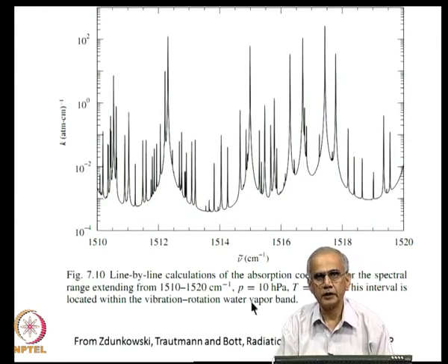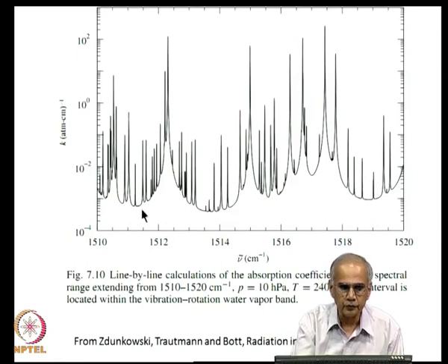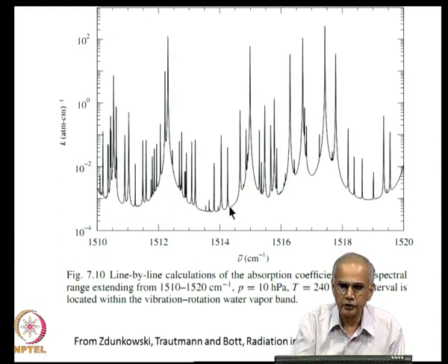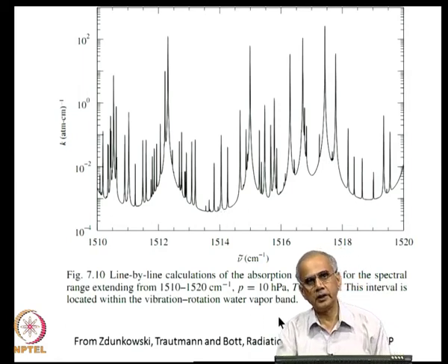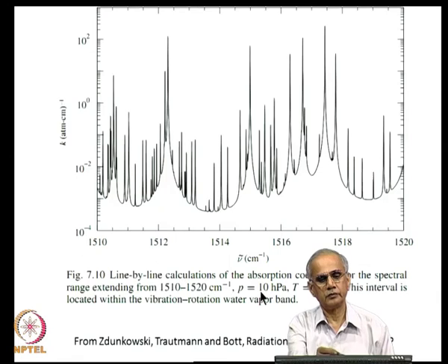So, this is a major challenge we face in calculating the absorption coefficient of gases, which is that there are a large number of lines, hundreds of them, and they go from almost 0 absorption to very large absorption, varying by a factor of 100,000 on a very short scale here. And so, in order to really capture the absorption lines here, you need extremely high resolution, and this is what makes the computation of absorption coefficient or computations in radiative transfer very complicated,